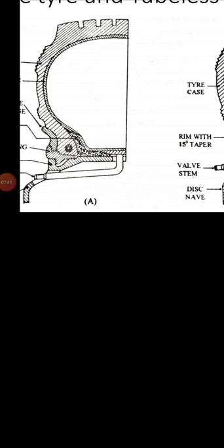The bead portion of the tire makes an effective airtight seal between the tire and the rim. The taper rims set on each side of the wheelbase, adjacent to the rim flanges, also assist the initial sealing between the beads and the wheel rims, basically at the time of inflation of the tire.